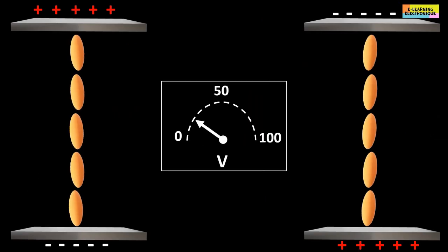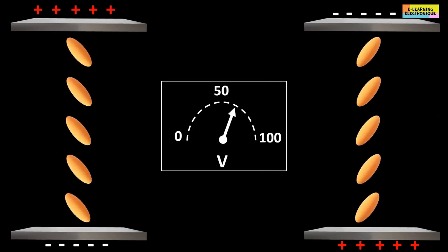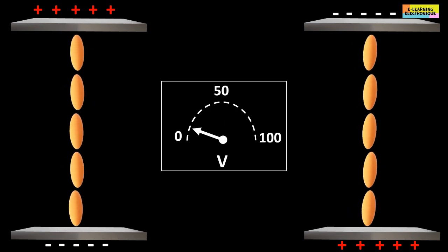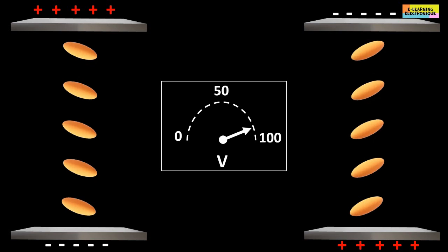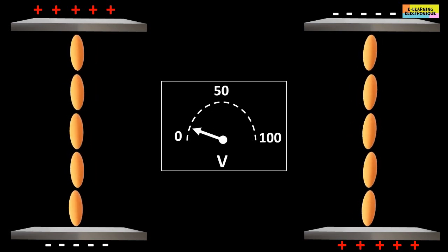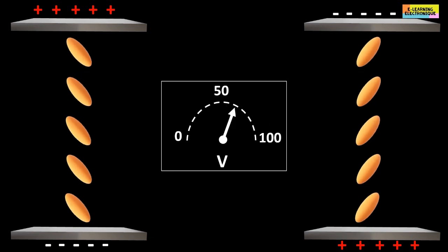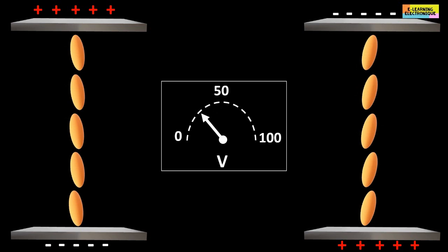To preserve this ability to change the orientation of the liquid crystal according to the voltage applied to it, the polarity applied to the electrodes is reversed. With the same voltage and reversed polarity, the same amount of light passes through the liquid crystal. The only difference is the direction of movement of the liquid crystal, which is different and does not impact the number of photons that cross the liquid crystal.